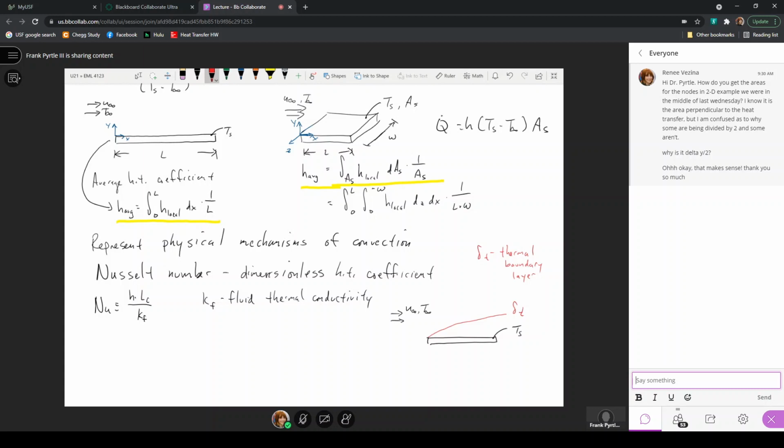This expression of the thermal conductivity is used to describe the heat transfer that will be occurring by conduction inside this thermal boundary layer, which would be in those stationary molecules at the very bottom here. The very bottom is the stationary set of molecules that are touching the surface. The heat transfer coefficient is associated with that heat transfer that will be occurring in the molecules that are actually moving. So right above that first layer of molecules, right on the surface, all the other molecules move.